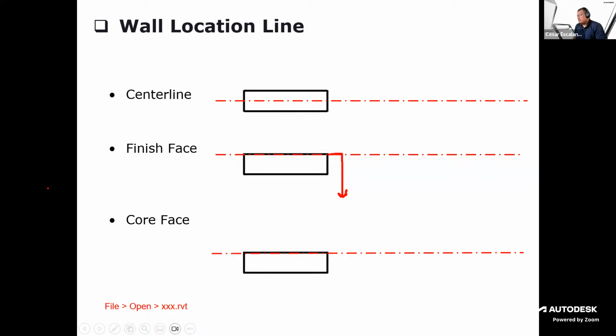And in some building types, it probably makes sense to use the core, because when it comes to dimensioning assemblies, there are some examples, in particular in metal buildings, where it doesn't matter where the finish is. What really matters is where the core lands. And for those technical people online, you're probably familiar with some examples where you use that logic.